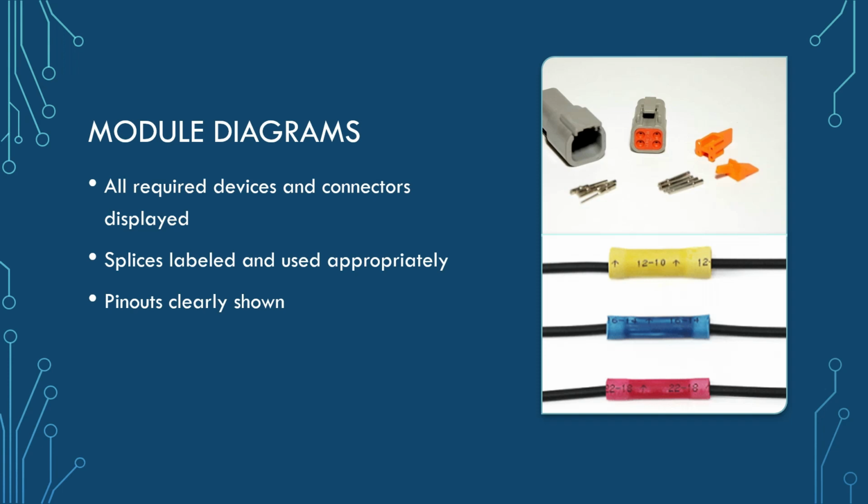And as I showed here, as I mentioned earlier with the splices and the nodes, instead of soldering a bunch of wires together, splices are easier for connecting 2 wires into one or vice versa, and getting certain power ranges. These are mostly used for power and ground, just because there are so many different devices on the car. You'll have one power going into that splice and then 2 branching off to 2 separate devices. So having those splices and not overloading them is important.